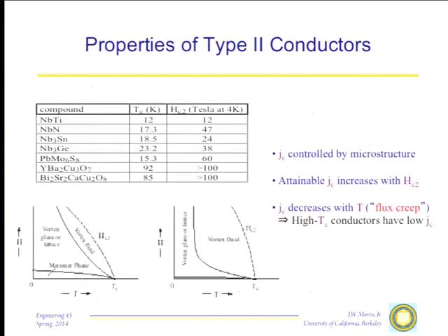Here, incidentally, are just some good type 2 superconductors. All of these materials have the problem that, because your Cooper pairs are coupling electrons to vibrations, you want materials that are almost unstable, that have big whomping vibrations. That means you're dealing with materials that are almost unstable. You then want to make them dirty. So good superconductors are lousy materials, and they're good superconductors because they're lousy materials. But that makes it enormously challenging to make them into wires that you might use in a practical way for various applications.